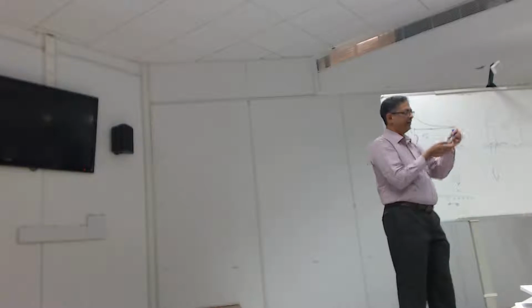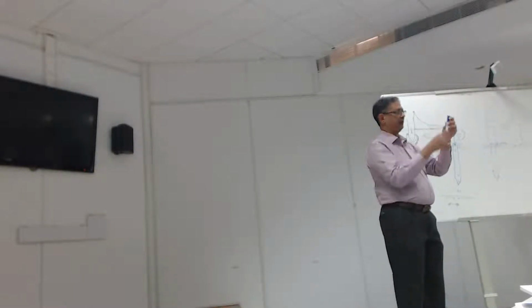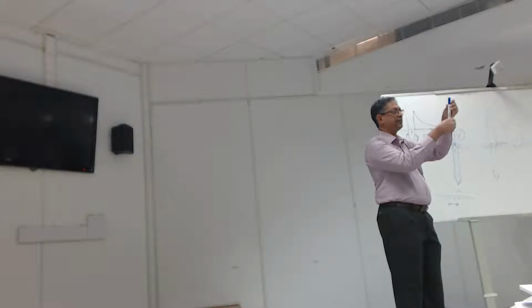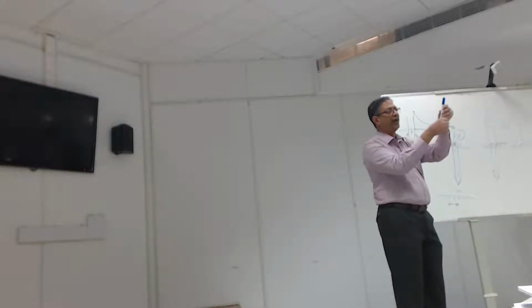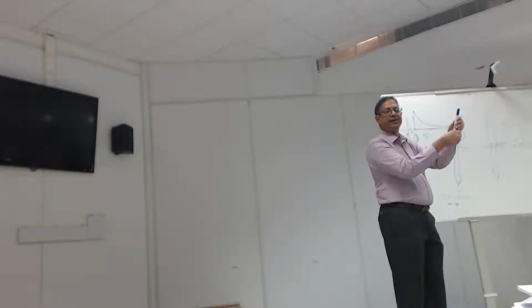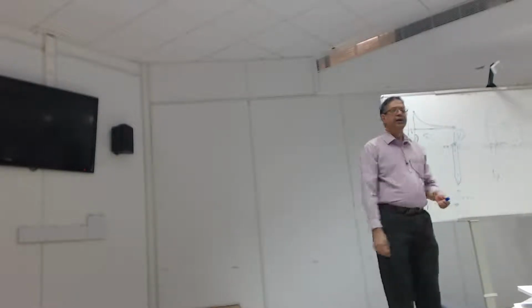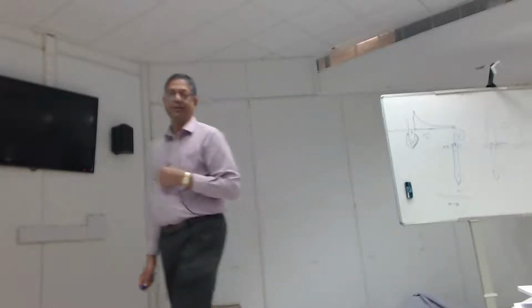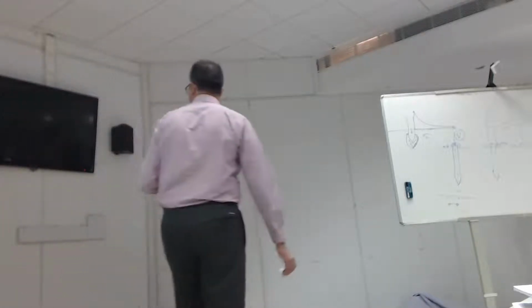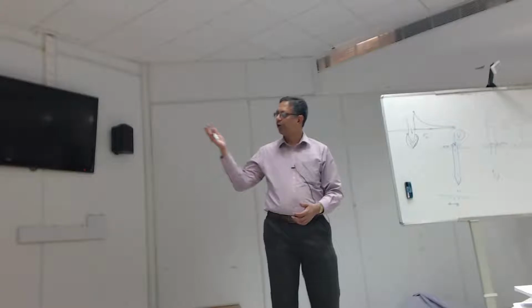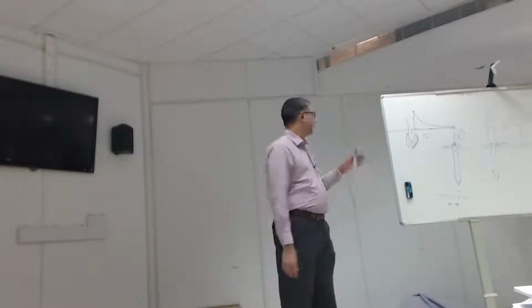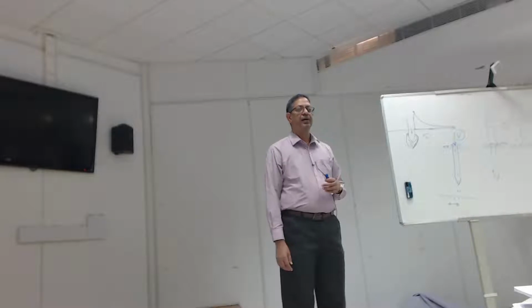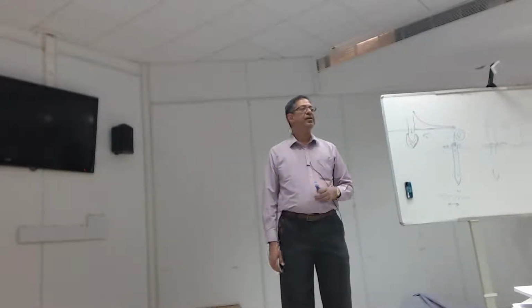So I have a big building sitting on the top, and that's trying to shake, and this is trying to stop it or not allowing it to go away. So I must get a resisting shear force or inertial force. Typically, you call this base shear. And so the first effect of having an earthquake loading on the pile is that it has to sustain this additional horizontal loading induced by the inertia of the superstructure. So that's called the inertial load.